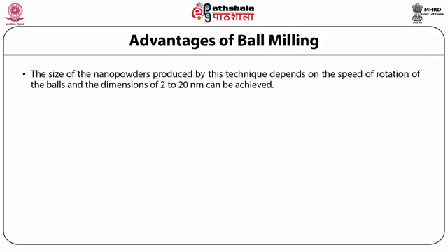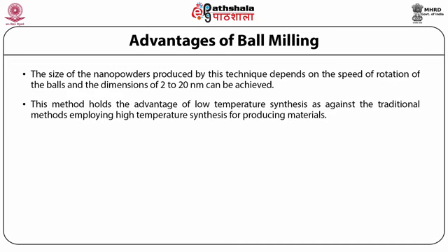The size of the nanopowders produced by this technique depends on the speed of rotation of the balls, and dimensions of 2 to 20 nanometers can be achieved. This method holds the advantage of low temperature synthesis as against the traditional methods employing high temperature synthesis for producing